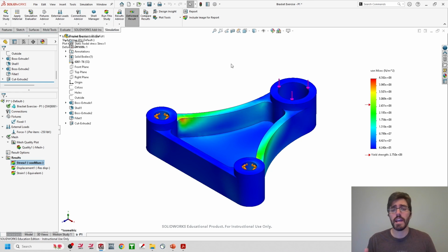those forces. And then as you go up this color chart, or this heat map here, you're going to see it progress into green, which is starting to increase the stresses or strains or forces being applied to those areas. And then when you start getting into yellow, orange, and eventually red, that's probably where you're going to start to get into failure points inside of this model when you apply those forces. So again, this looks pretty good on a first pass, first glance.